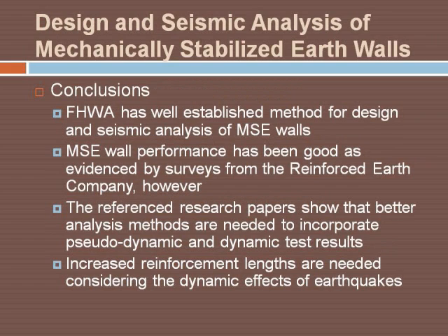In conclusion, I've found that the Federal Highway Administration has well-established methods for design and seismic analysis of these walls. Performance has been good. The wall performance has been good in earthquakes. The referenced research paper indicates that better analysis methods are needed to incorporate pseudo-dynamic and dynamic test results, and increased reinforcement lengths are needed for the dynamic effects of earthquakes.